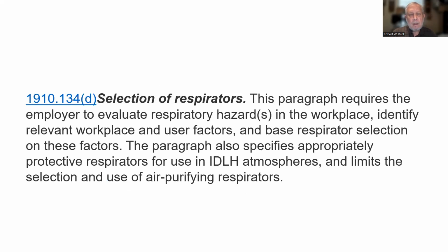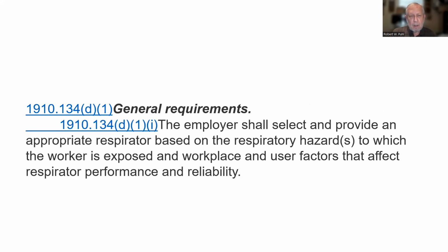No surprise there. Selection of respirators. This paragraph requires the employer to evaluate respiratory hazards in the workplace, identify relevant workplace and user factors, and base respirator selection on these factors. The paragraph also specifies appropriately protective respirators for use in IDLH atmospheres and limits the selection and use of air purifying respirators. General requirements: the employer shall select and provide an appropriate respirator based on the respiratory hazards to which the worker is exposed and workplace and user factors that affect respirator performance and reliability. So obviously, before you do this program, you have to know what kind of hazards you're looking at here.